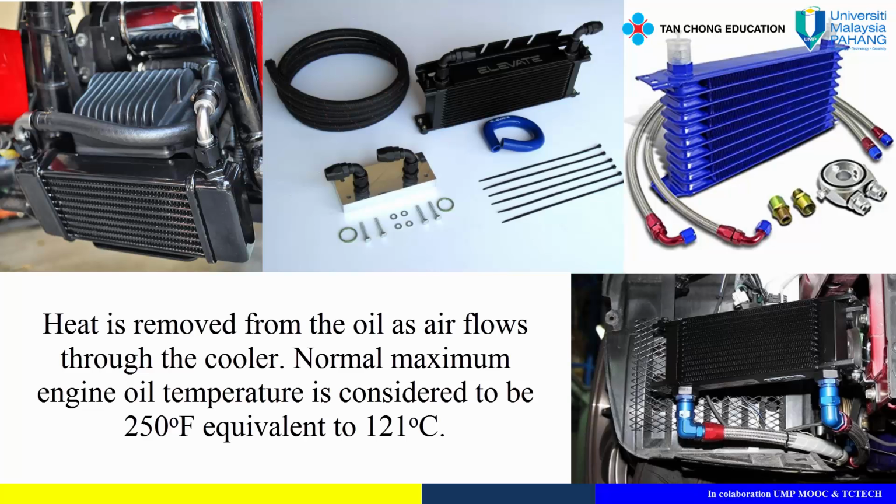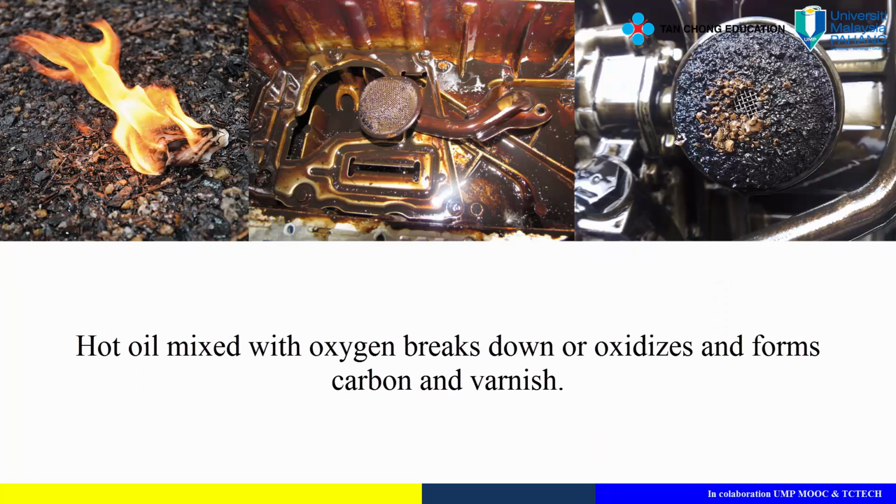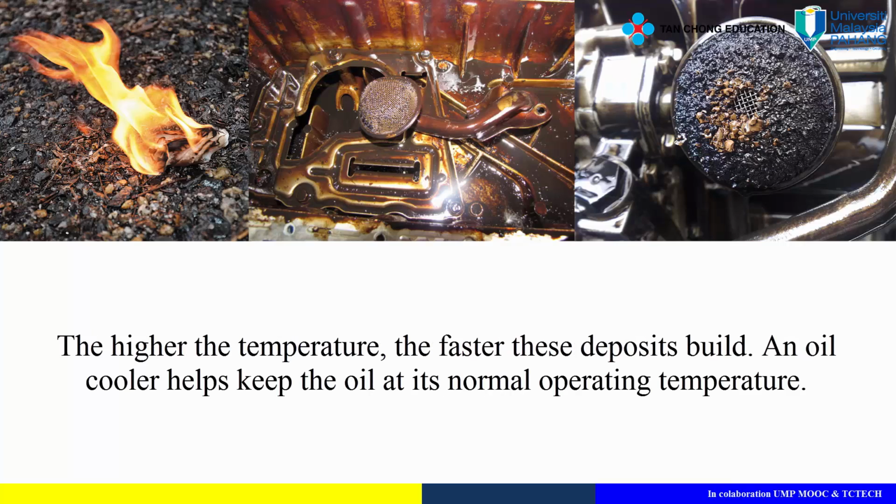Normal maximum engine oil temperature is considered to be 250 degrees Fahrenheit, equivalent to 121 degrees Celsius. Hot oil mixed with oxygen breaks down, or oxidizes, and forms carbon and varnish. The higher the temperature, the faster these deposits build. An oil cooler helps keep the oil at its normal operating temperature,